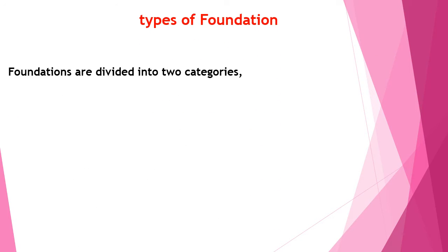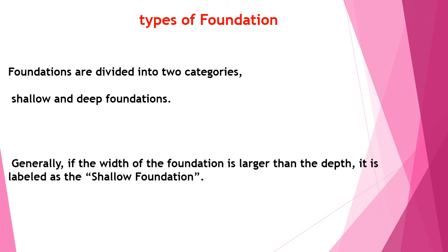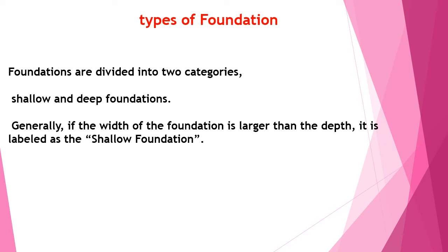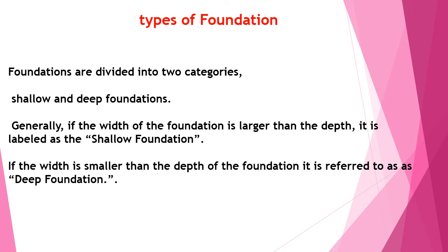Types of foundations. Foundations are divided into two main categories, known as shallow and deep foundations. If the width of the foundation is larger than the depth, it is known as a shallow foundation. If the width is smaller than the depth of the foundation, it is known as a deep foundation.